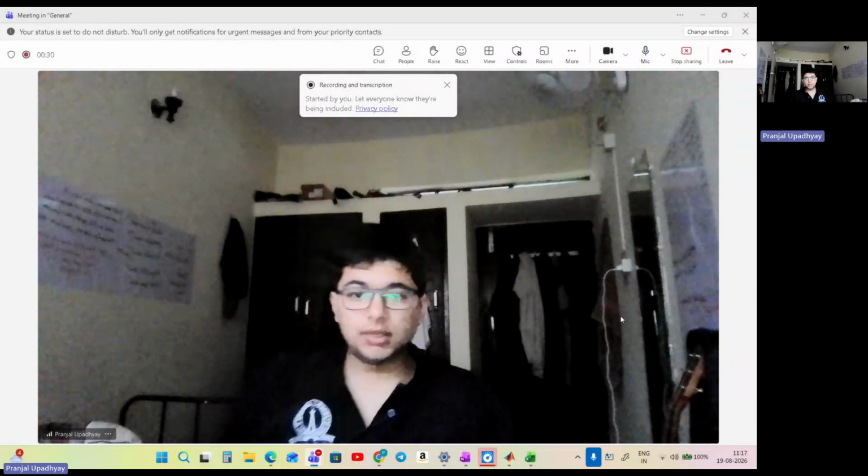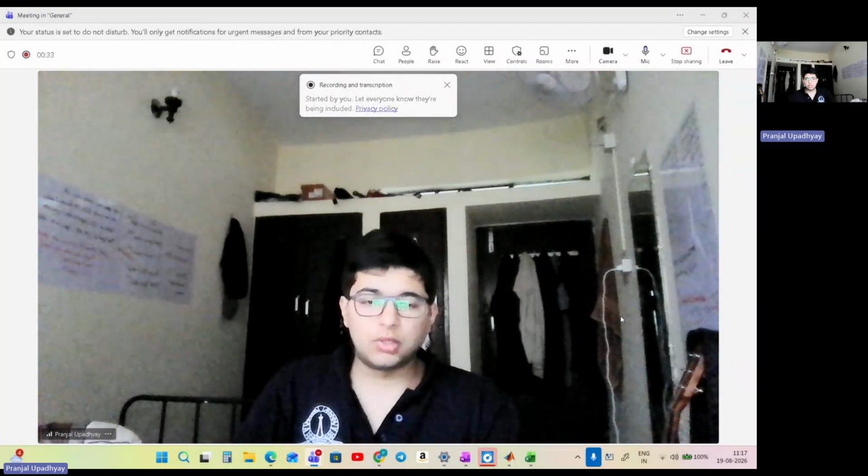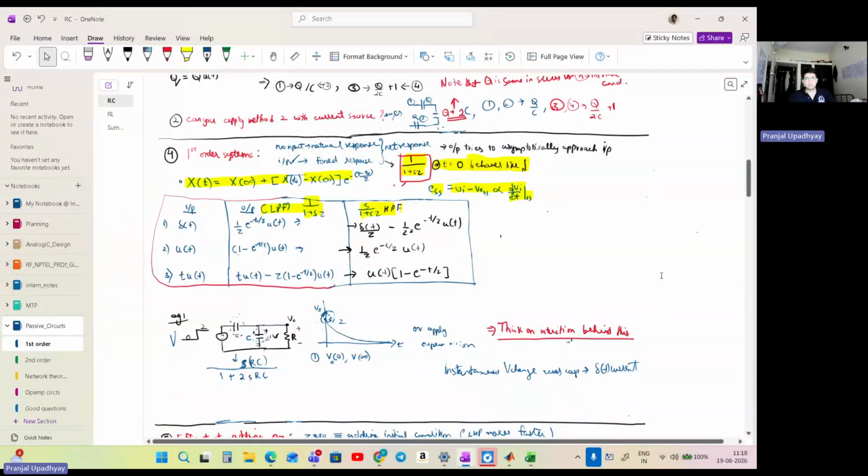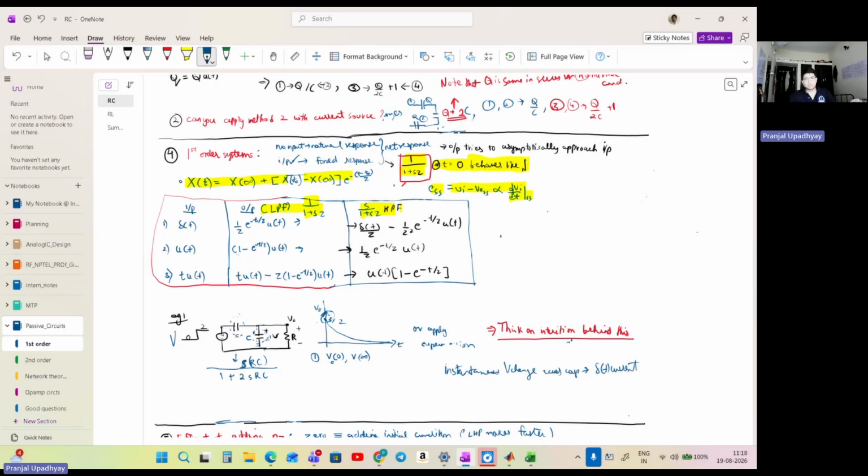So hi, and in this video, let us just continue off from where we left in the previous video. In the previous video, we basically discussed till the basic response of the standard first order low pass filter, and now I have just drawn the response of a standard high pass filter also for comparison. As we can understand, the only difference here is that this high pass filter has a zero at DC, right? So it has a zero at DC.